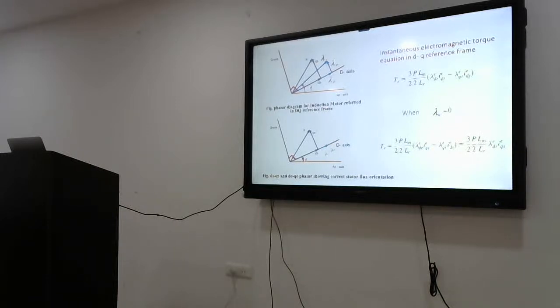Most electric vehicle applications, industrial applications, and traction applications in foreign countries, except in India, are adopting this method. But coming next 3 or 4 years, definitely in India also they are trying to replace DC series motors with induction motors with the FOC method, field orientation method.